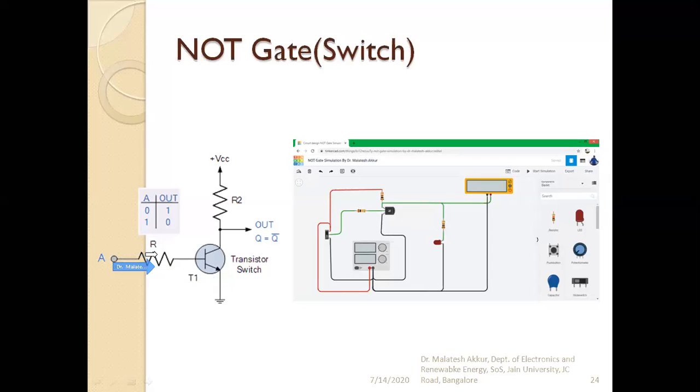So this resistor plays a very important role. Usually this resistor is taken as a higher resistance. It has to limit the current to the base of the transistor, and it also provides the path for the voltage drop across it, which is the excess beyond the knee voltage. The knee voltage is enough for this transistor to conduct. Conduct means it becomes on. Once it becomes on, I'll repeat once again: when it is 5 volts, the EB junction becomes forward biased.